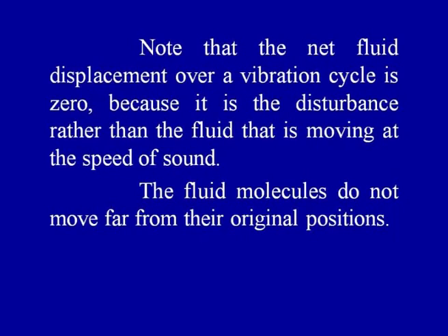Another thing to be noted, when a sound wave is passing, the net fluid displacement over a vibration cycle is 0, as much movement on one side as on the other side during a vibration. It is the disturbance rather than the fluid that is moving at the speed of sound. The fluid molecules do not move far from their original positions. Those displacements are very small.